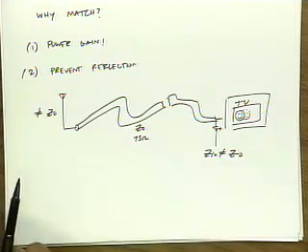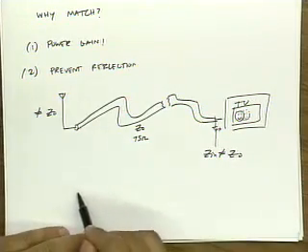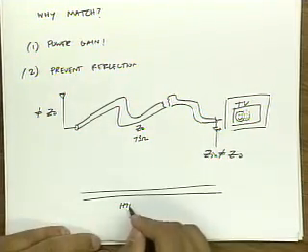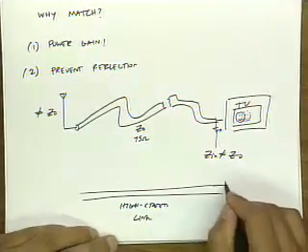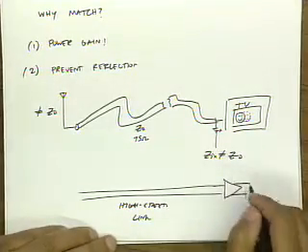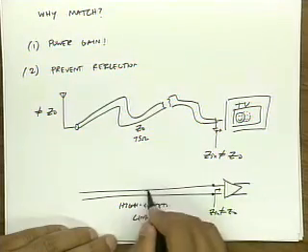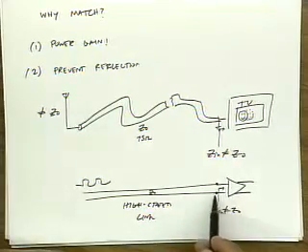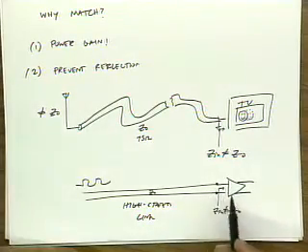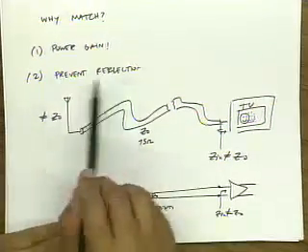Another example is a data communication system. If I'm sending high-speed bits over a high-speed link and I have an amplifier at the end of the link, and the input impedance is not equal to Z0, then this data gets reflected and actually produces intersymbol interference. So it gets harder and harder to correctly detect these bits. So there are many situations where we terminate to prevent reflections.